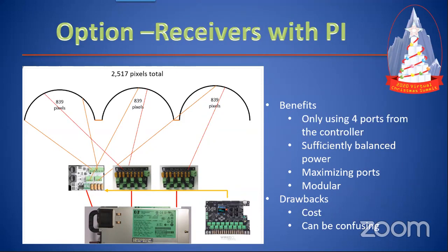So I think another misconception is, using your calculator is good, but again, you have to know what your draw is, right? And that draw is typically calculated at full on running, so running full white. That's going to be your draw. And even power supplies are rated, John, correct me if I'm wrong, but typically they're only showing you that 80%. There's always a 20% overhead.